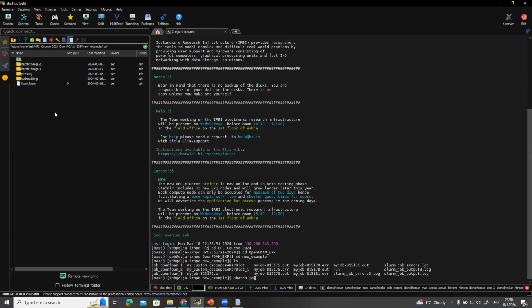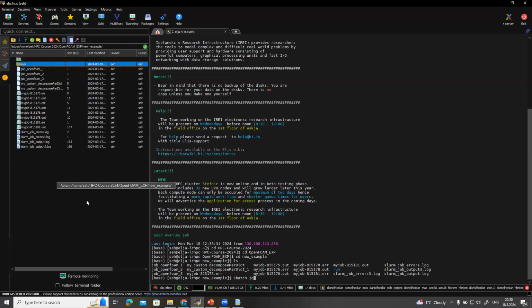So we don't have them anymore here, because when there's a copy from them, because the decomposition is done, you will get an error. The copy is fine, but when the decomposition is running, because it will see the decomposed subdomains as available, it will get an error and stop the simulation from running.